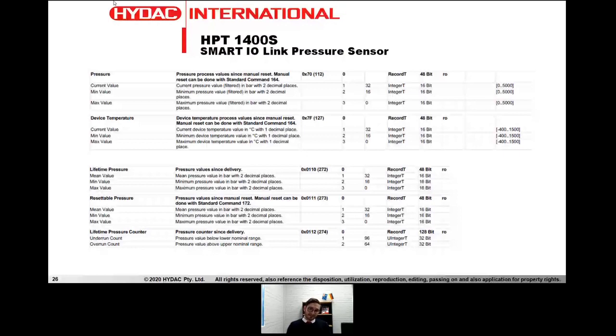You can also, because as I explained earlier, we do temperature compensation on the sensor for linearization. And since we do temperature compensation, to do that, we need a temperature sensor. And that temperature sensor sits inside the cell on the electronics part, so we can actually measure the temperature and give a good representation of what the fluid is, but I wouldn't use it as a temperature controlling device. But you can use it to actually see if the sensor is going above temperature itself, and you can record that value, and maybe you can calibrate the temperature value of the sensor to your process, and you may actually be able to use it as a controllable something to control your process.